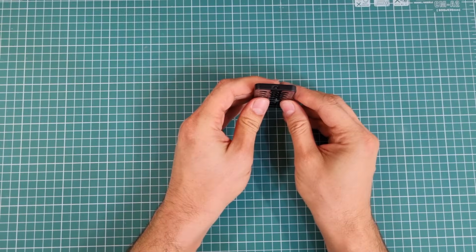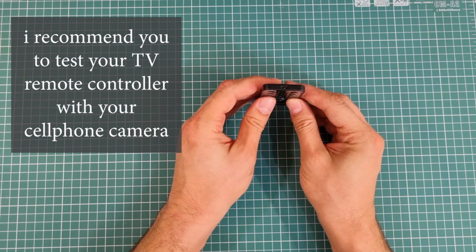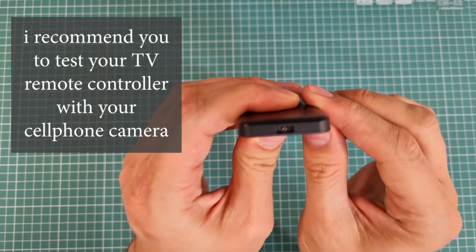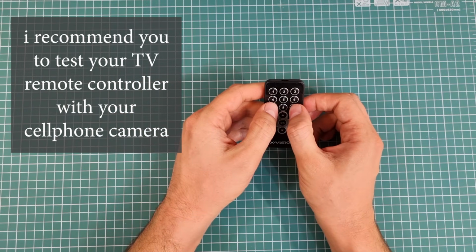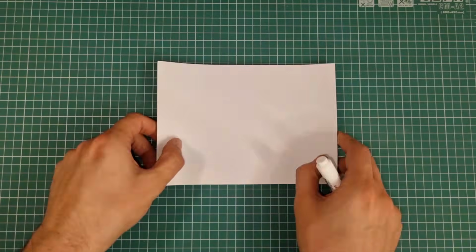If you look at your TV remote controller, you cannot see anything, but here the pulses are visible because they are visible to a camera, even your cell phone camera. We saw the pulses, but how do they work, and how can we use a remote controller in our project? There are IR remote receiver components on the market in various shapes, types, and part numbers, but one of the most popular is this one, with 3 pins. Two of them are for powering up the component, and the third one is for data output.